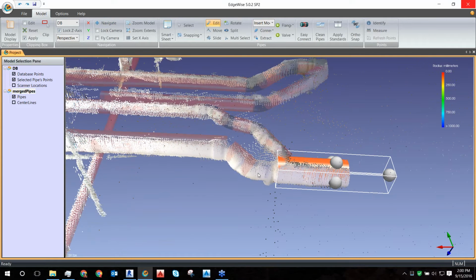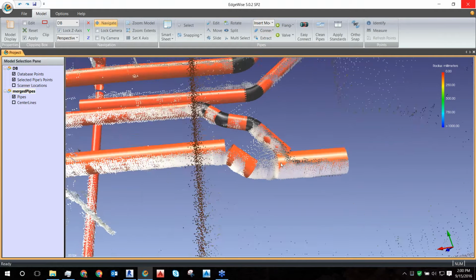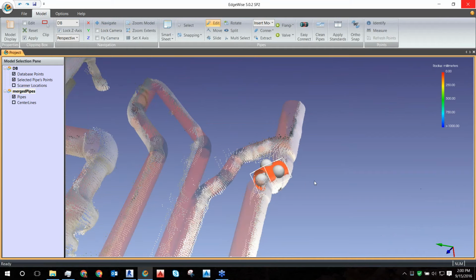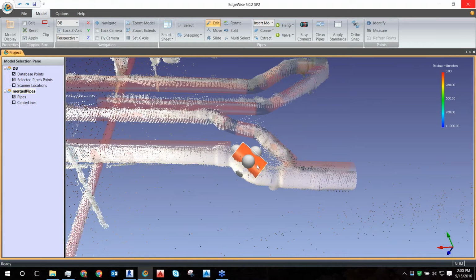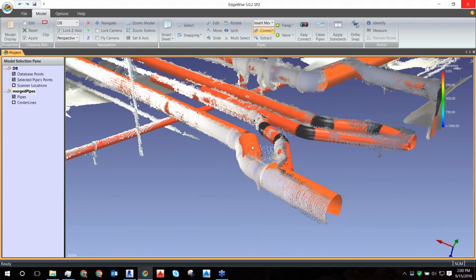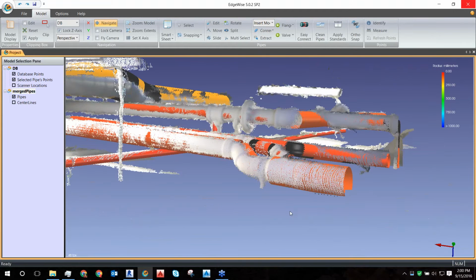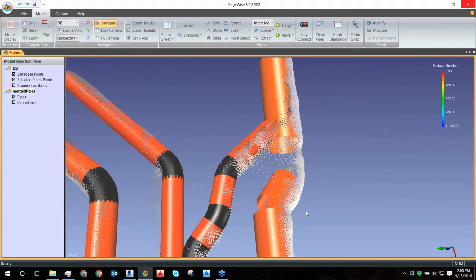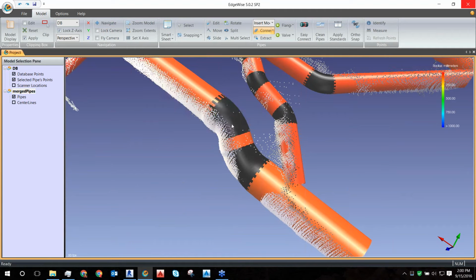I'm happy to jump in on that, Kevin. What we recommend: the sweet spot for distances is to be 1 to 2 meters, or 3 to 6 feet, away from whatever it is you're looking at. That's a good compromise between getting the level of detail that you need and allowing the device to track successfully. As far as lighting, we get the best results in conditions that are lit appropriately for a photograph or a video camera. And if that lighting is absent, then we strongly recommend using our onboard light kit.